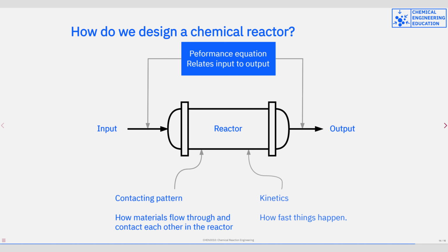Kinetics, the study of reaction rates, is a fundamental aspect of reaction engineering. If reactions occur quickly, equilibrium conditions will largely dictate the reactor's output. For slower reactions, the reaction rate alongside heat and mass transfer rates become significant factors in determining the reactor's performance.